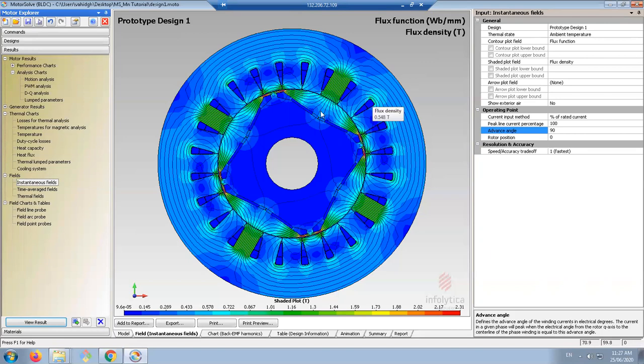Depending on the rotor topology as well as the permanent magnet volume, you may be able to operate over 5-10 times the rated speed, maybe 15,000, 20,000 RPM. We also have ultra high speed motors, which operate over 100,000 RPM. So this is the technique that people use to guarantee that they can get a high speed level.